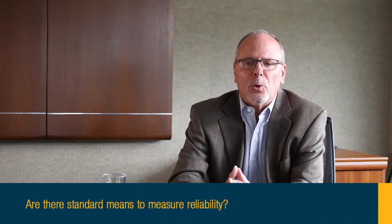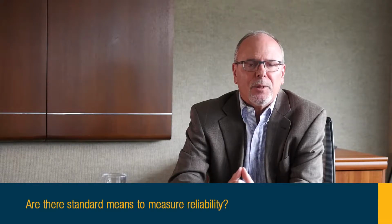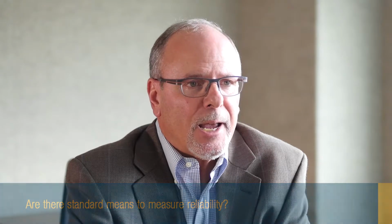There are standard measures for reliability. There are some that are recognized by the industry that are usually measured at the utility's service entrance, and these typically have to do with availability, dealing with things like outage minutes and frequency of outages. And then also once you get into your on-site infrastructure, the IEEE, the Institute of Electrical and Electronics Engineers, also publishes standards that actually get down to availability, which basically puts it out to the number of nines percentage of time that your utility infrastructure is available for you to use, and there are equations and methods for calculating that based upon the amount of redundancy that's in your system.